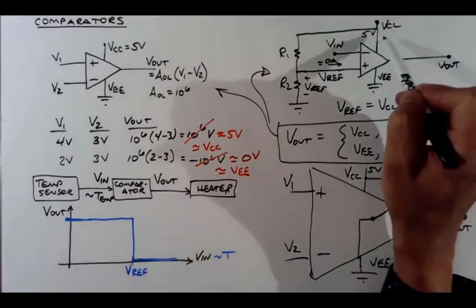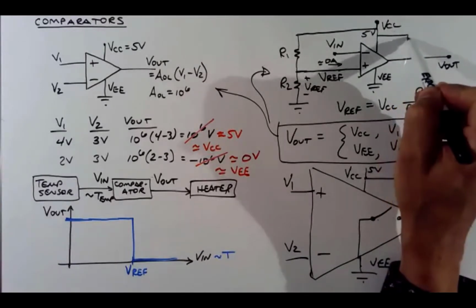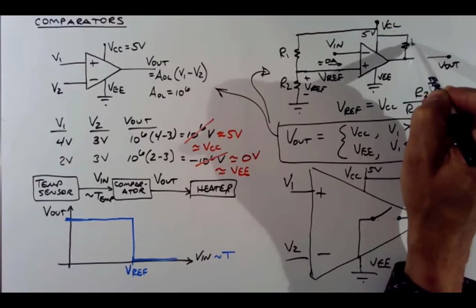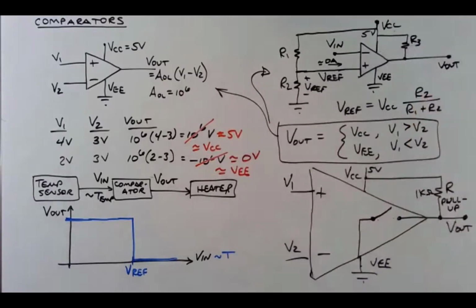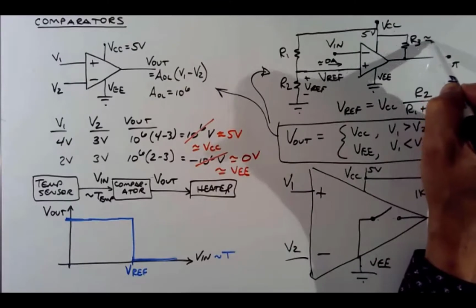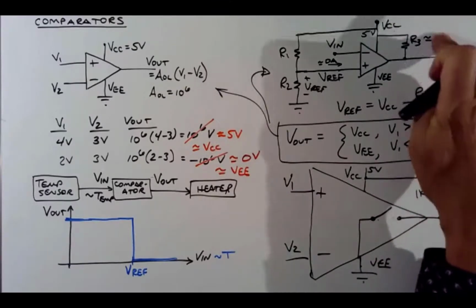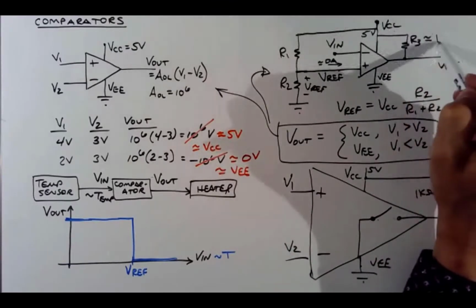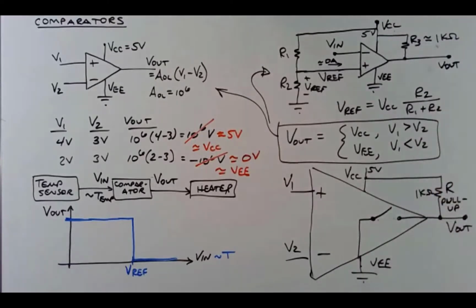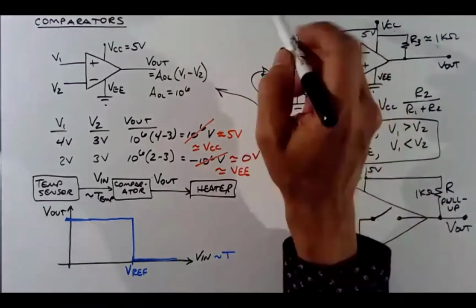So you need a resistor here if you're using a specialized comparator chip, and that would typically be in the 1 to 10K ohm range. Let's just write a 1K ohm resistor here. So that right there is the schematic for what we call an inverting comparator.